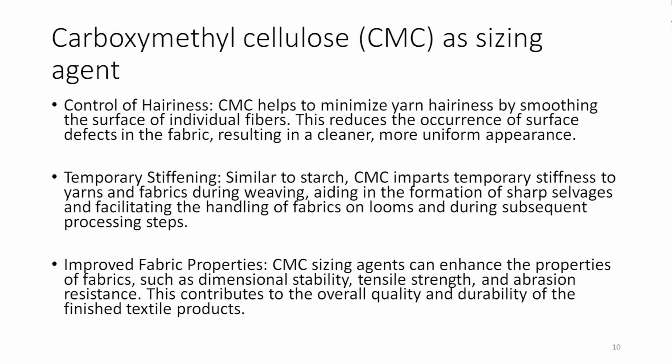Temporary stiffening. Similar to starch, CMC imparts temporary stiffness to yarns and fabrics during weaving, aiding in the formation of sharp selvages and facilitating the handling of fabrics on looms and during subsequent processing steps. So, just like starch, even CMC can give temporary stiffness, which is required for handling at that stage.